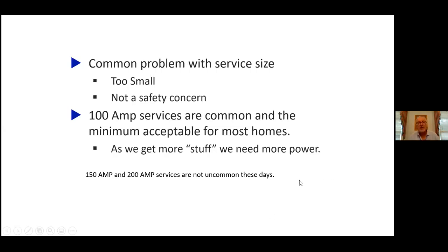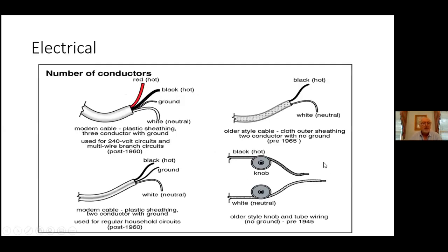And you'd need more power in order to wire it all in. You would need to have a sub panel. And depending on how much equipment you were actually planning on putting down there would determine how much more power you needed and how big of a sub panel or an alternative panel you would need. So back in the day, let's look at this little schematic here.